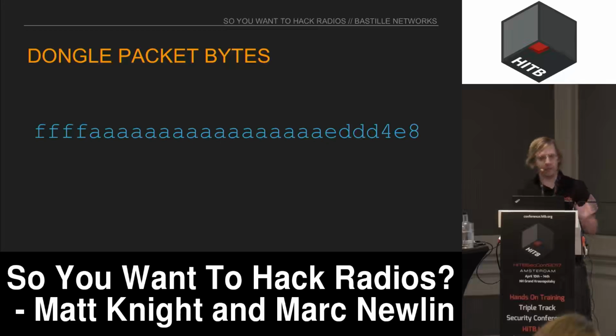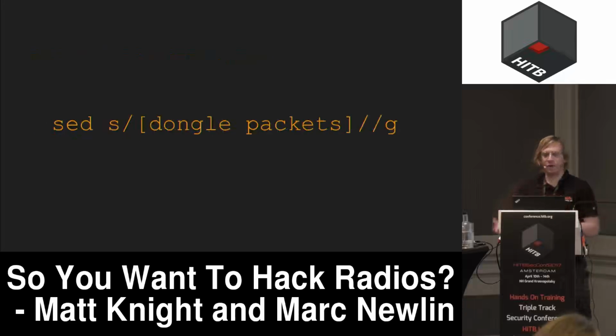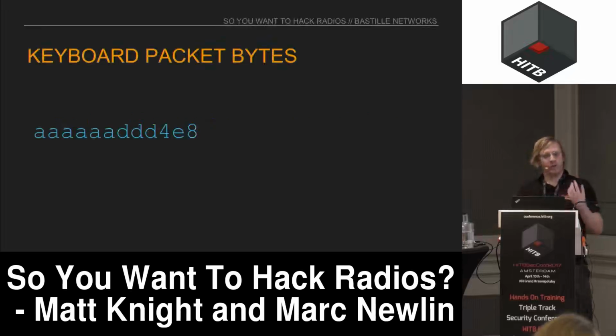And this is pretty great, because then we can do another capture with the keyboard and dongle. We can use sed to replace the dongle packets from the dongle plus keyboard packets, and then we have a file that has presumably only the packets that are sent by the keyboard. So we can run that grep command again, and now we have something different. We have a shorter preamble, and then we have slightly different address bytes, or first 4 bytes of the frame, that the keyboard is sending.